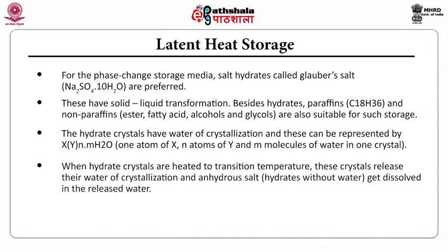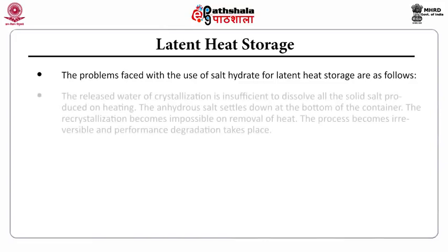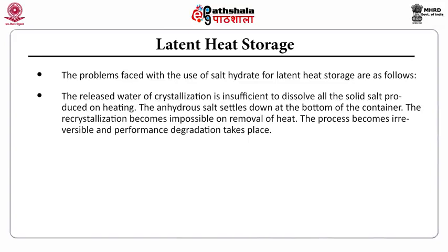When the hydrate crystals are heated to transition temperature, these crystals release their water of crystallization and anhydrous salt, that is hydrates without any water, get dissolved in the released water. But the problems faced with the use of the salt hydrate for the latent heat storage are: the released water of crystallization is insufficient to dissolve all the solid salt produced on heating. The anhydrous salt settles down at the bottom of the container. The recrystallization becomes impossible on removal of heat. The process becomes irreversible and performance degradation takes place.